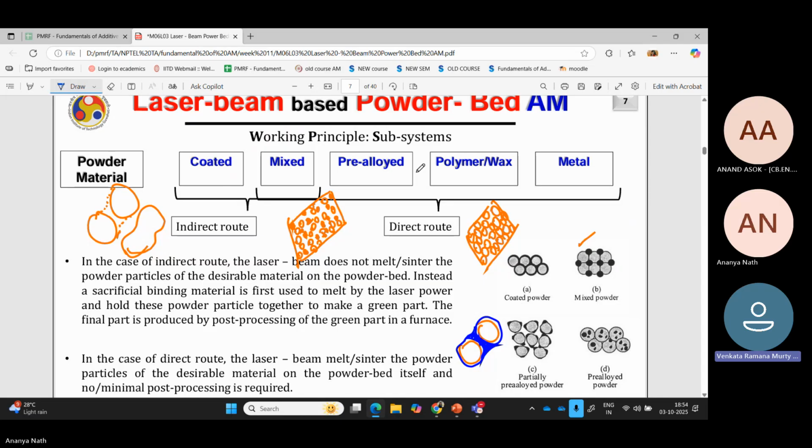Normally, sintering is meant for ceramics only, mainly. Yeah, that is the normal sintering where you apply the pressure and everything. Here, with metal using laser, you are doing it. So application of pressure may or may not be there. Both are possible. But sintering here means that you are not melting it. You're just fusing two powder particles together.